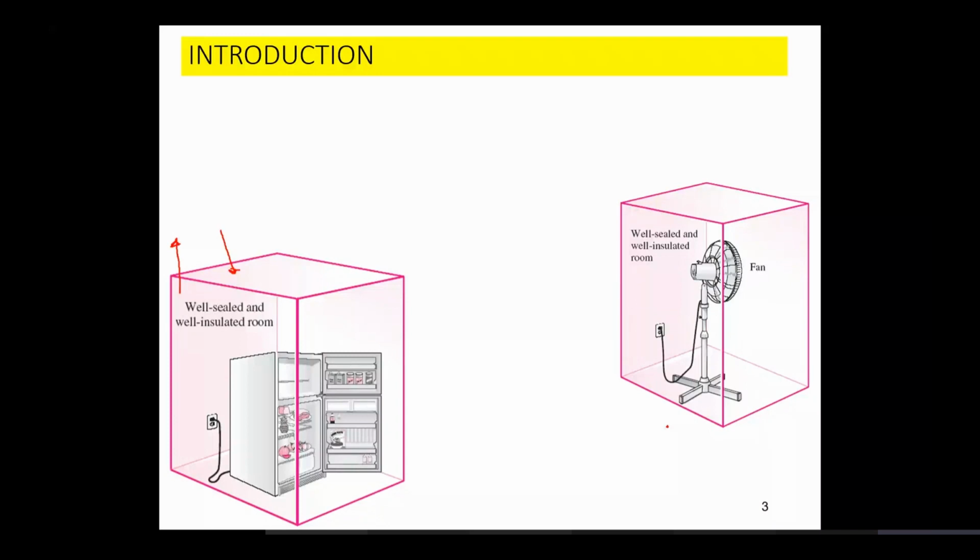So even if I know just the first law, the first impression I should get is that energy which is coming into the room and is not able to get out of the room has to get stored within the room. If the refrigerator is not storing it, if the pedestal fan is not storing it, then the only thing left to store it is the space of the room or the air of the room. That will store the thermal energy within the room. So the temperature would eventually go up. Clear? All right.